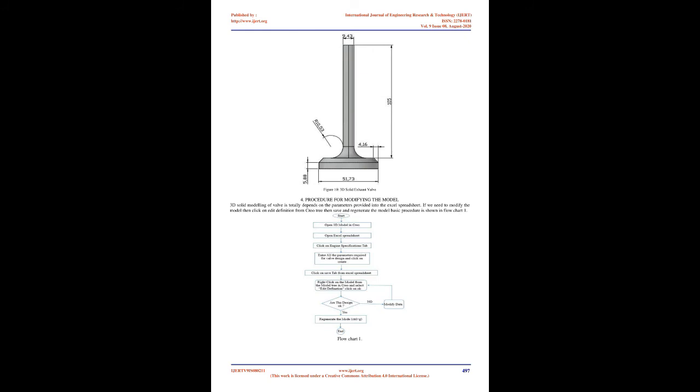Finally, we integrate the Excel spreadsheet and Creo Parametric to automate the design and solid modeling generation tasks. The user is now ready to make a solid 3D object of an exhaust valve by just entering the input parameters needed to design the exhaust valve into the Graphical User tool by clicking on the Engine Specification button from the Excel spreadsheet. The Graphical User tool will automatically calculate the dimensions of the exhaust valve and save them into the Excel spreadsheet.